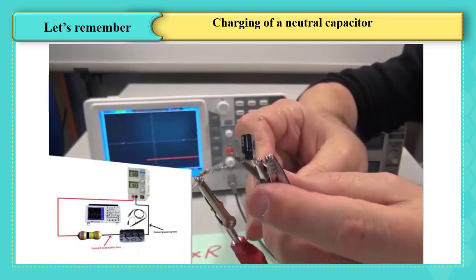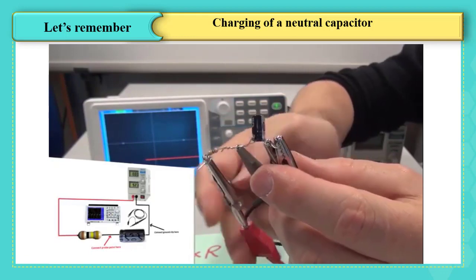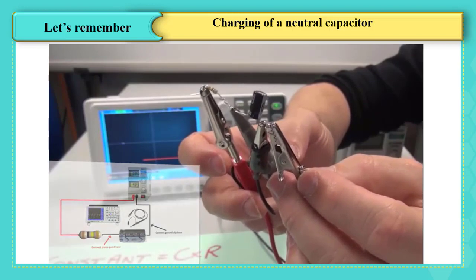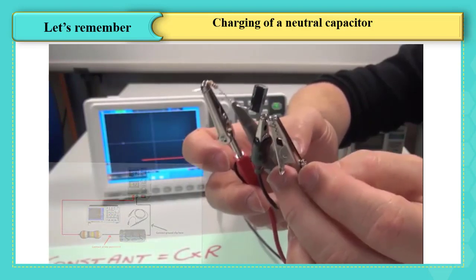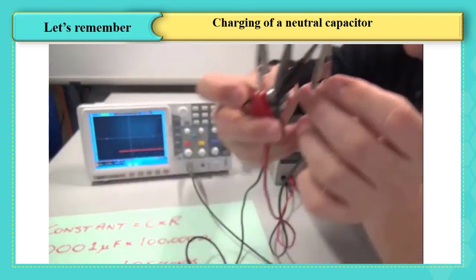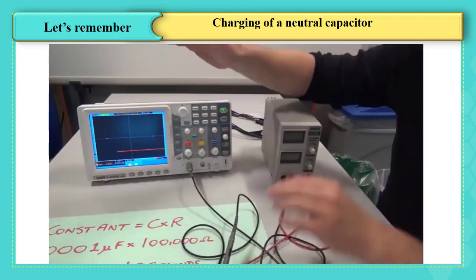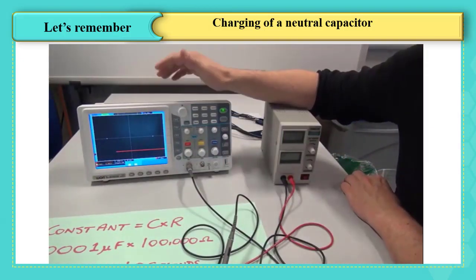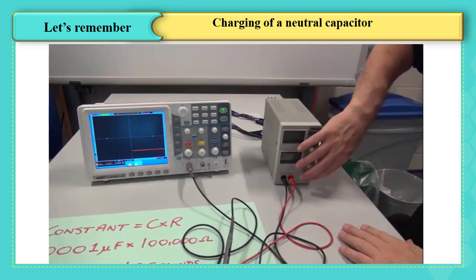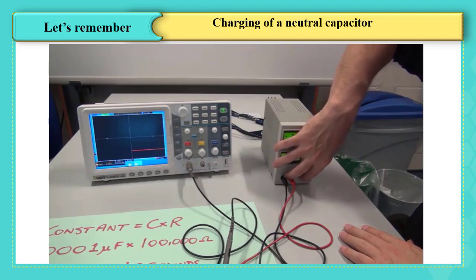And the probe itself connects to the other side of the capacitor like that. And that is all you need to do to set up the connections for this circuit. Just make that a little bigger, so you can see that a little better. Now that the circuit's set up, we are interested in the reading on the oscilloscope. So we press the power supply on.